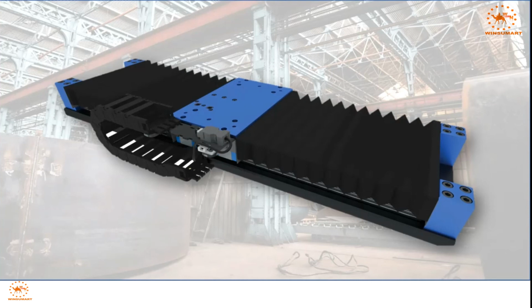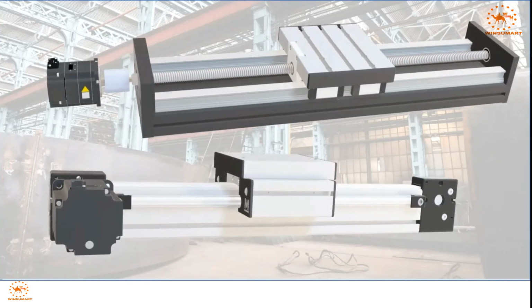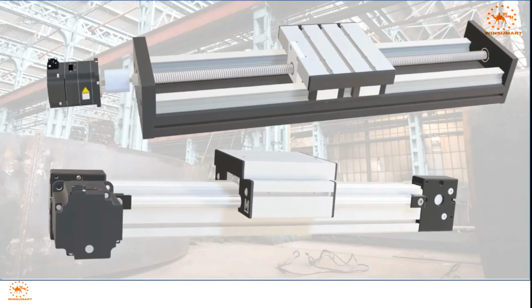The linear scale can still work with some interference, but for very dirty environments, consider a custom linear motor with an inductive or magnetic linear encoder. The ball screw is used commonly in machine tool and other dirty environments, although the screw must be protected. Belts and rack and pinion also work well in many environments.